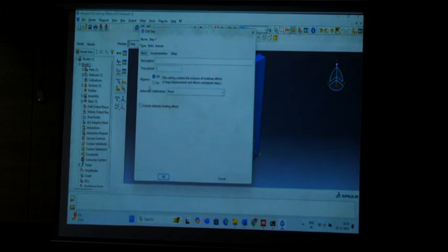So here if you can see NLGEOM, by default it will take the option off, but sometimes we have overhangs, I mean large deformations. If it is straight, then we are going to keep the load perpendicular to the exact surface, but sometimes it will deform, in which some of the lower edge will go inside.